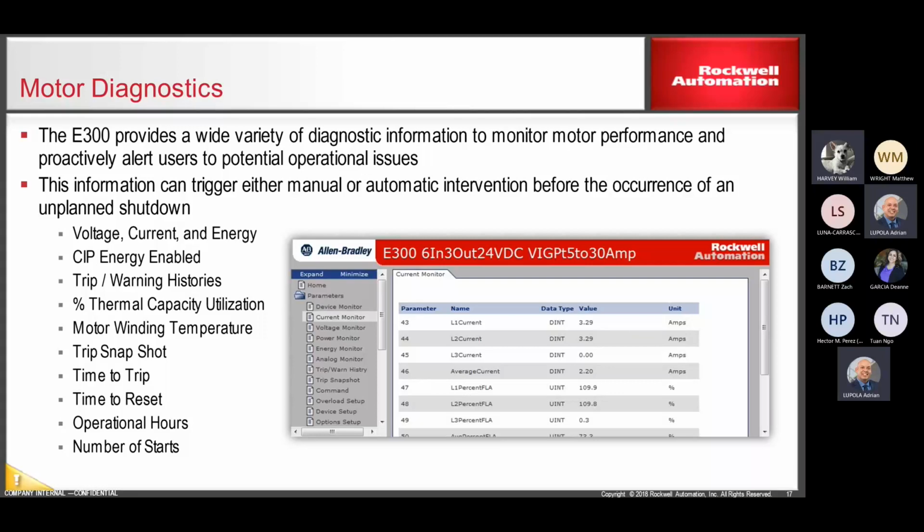But you can see how the motor's running, and you set parameters. So if it starts to run, maybe a conveyor is getting overloaded, or a mixer, the batter, the dough is getting too thick or something like that, the current's going to start to creep up. But I don't want to wait till I snap a shaft or something breaks or it just stops. So you can set a pre-warning. As things start to get up, maybe if it's an in-feed conveyor, it has to back off a little bit so the load on the conveyor doesn't get too strong. So you can do some logic in this and control what's going on. But again, also do something before it shuts down.